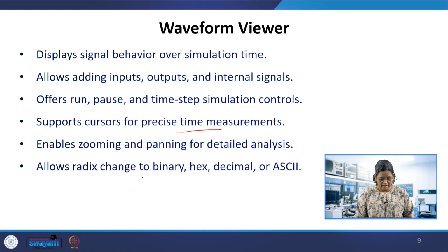Also, it allows radix change. Suppose in the $monitor or in the code in the test bench, you use binary, but you want to see that value in hex, decimal, or ASCII. There are formats in which this can be viewed as well. So it allows radix changes of the viewed signals.